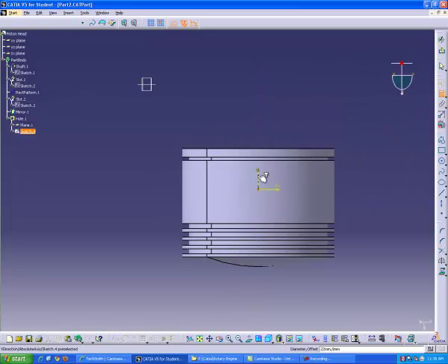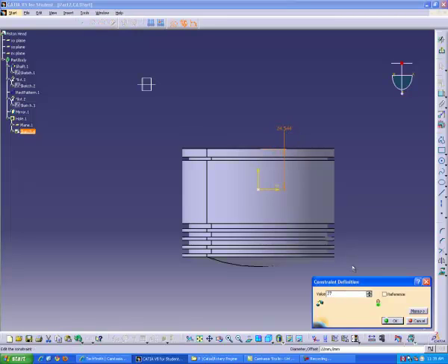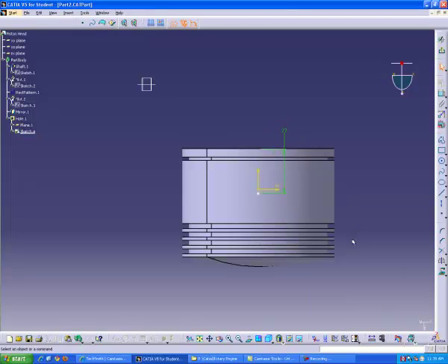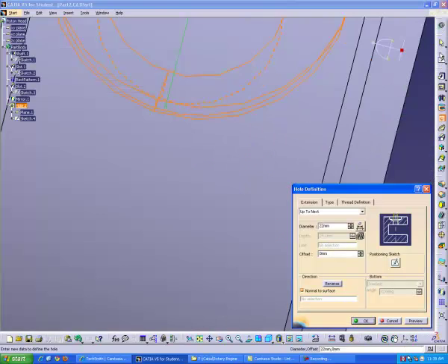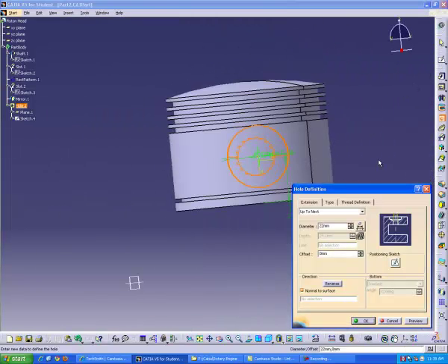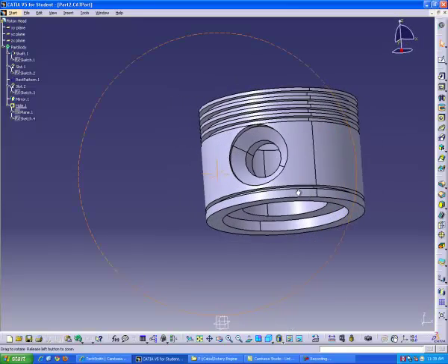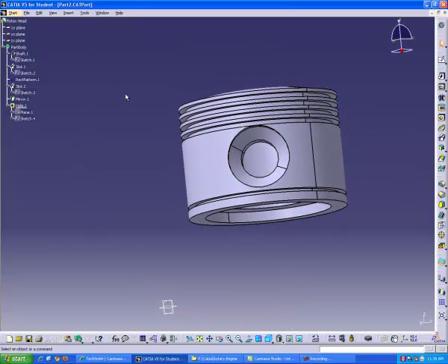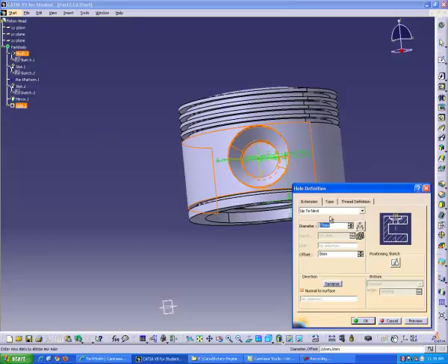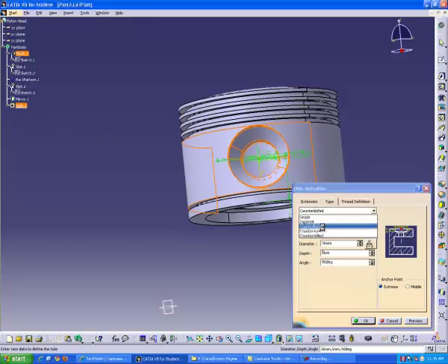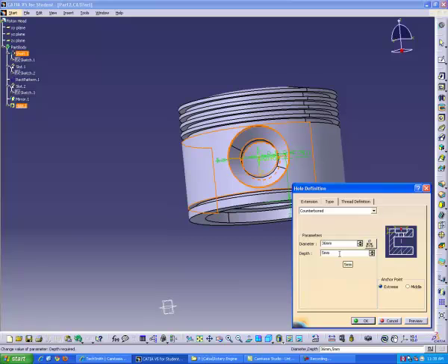Enter the sketch for the hole command, and make sure that the distance, the center of the hole, is 27 millimeters from the bottom edge of the cylinder head. Looks good. Preview it. Okay. There's our first hole. Make sure it's counterbored.